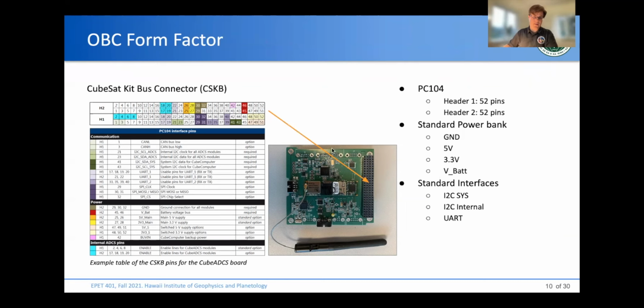And so for the CubeSats, we have developed this CubeSat Kit bus connector over the years within the community to standardize what we mean by the power and the data for these connectors, so that if you buy a board from another vendor, in principle, it should match your connector. But due diligence is important, so you always have to check and work with the vendor to make sure that you are getting the right interfaces. But here are some typical examples.